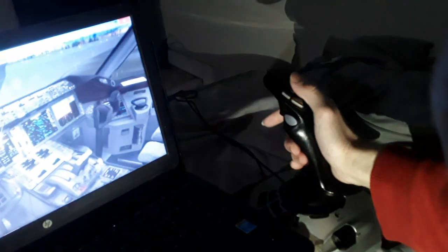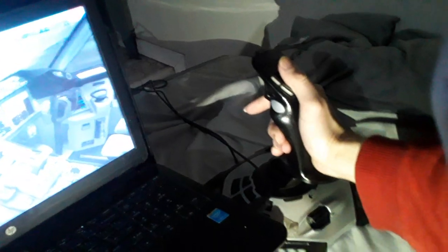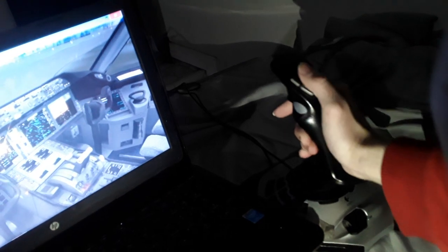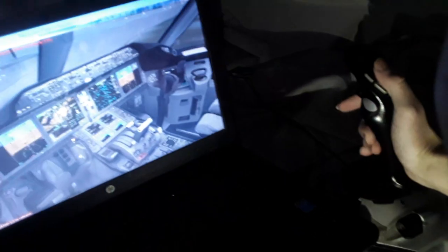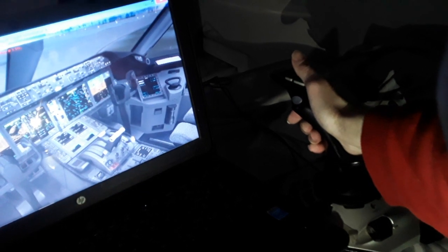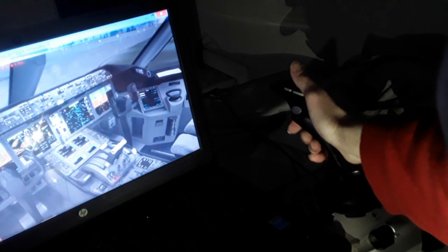So when we fly in the normal mode, all flight controls are limited in terms of G acceleration, where G is the acceleration of the Earth's gravity. So when we climb, descend, make turns or stay in level flight, we have the acceleration calculations. In the Airbus, you move the side stick up, you climb 30 degrees up or 1.5 G. Also you can descend: you push the side stick down, minus 15 degrees or minus half G.